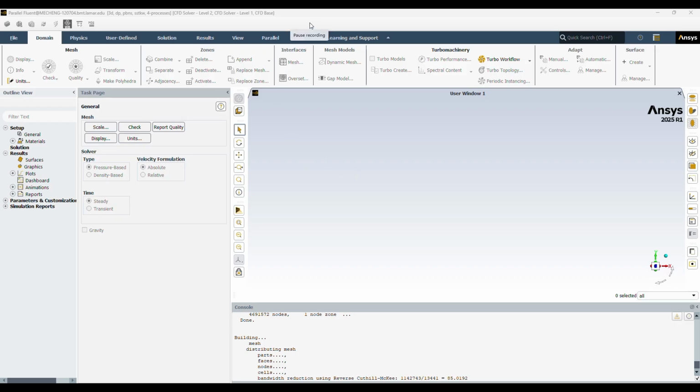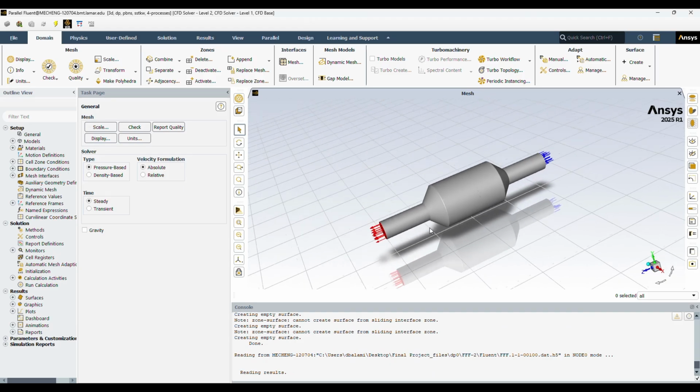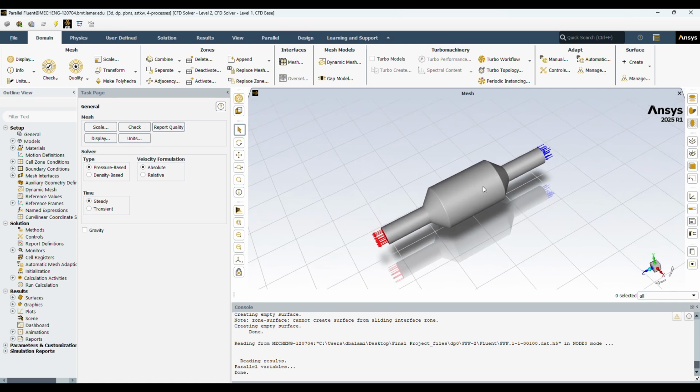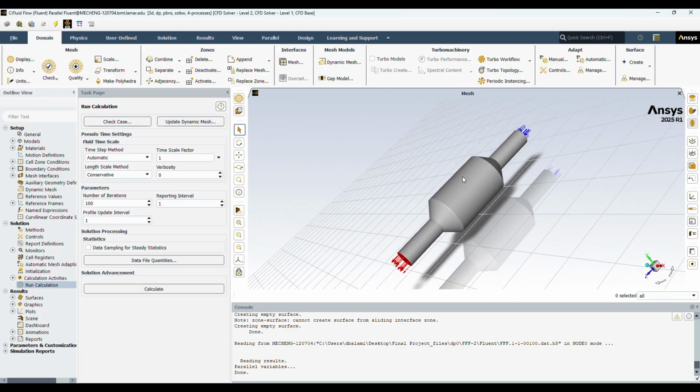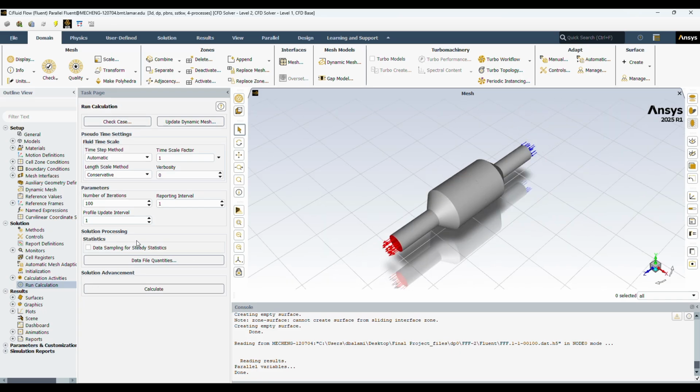Here the meshing nodes were much more than a million. That's why you need to have a good version of Ansys Fluent. The student version is not capable of doing a good mesh of more than 1 million. So this is the required solution geometry with the barrier in between. All the activities are the same as before, just the geometry is being modified in between, having the honeycomb structure.